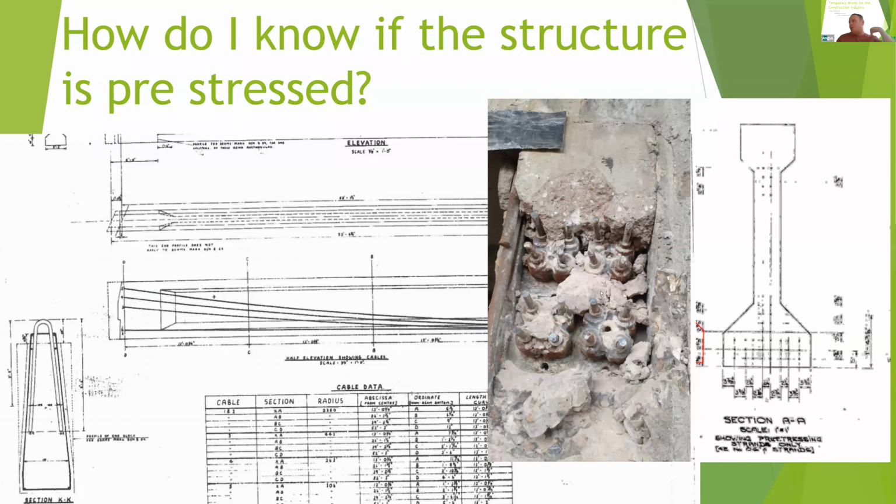So this was an interesting building in London where the whole structure was done in precast concrete, and the spans were such that we thought they might well be pre-stressed, and a bit of investigation on site made it quite clear that they were, and that was the anchorage system that was found. But again, there's no other means of telling. There were no drawings for the site. There's no plaque anywhere telling you. It just came down to getting on site and having a look.